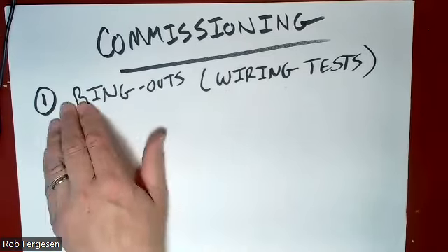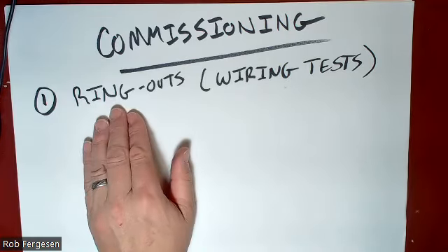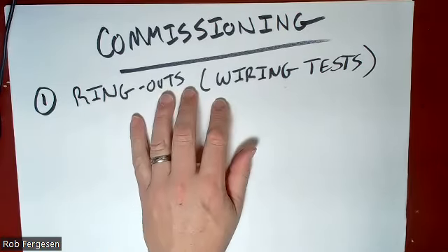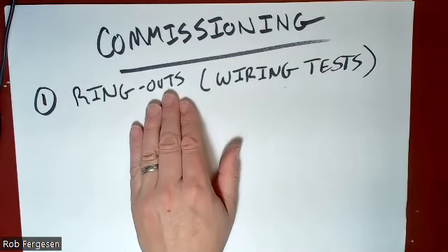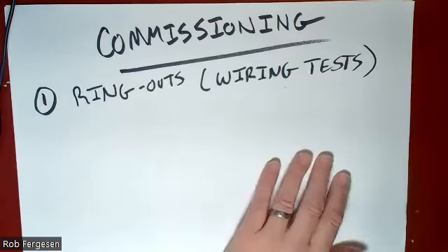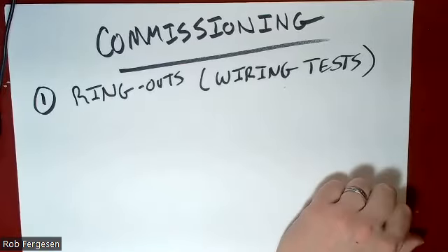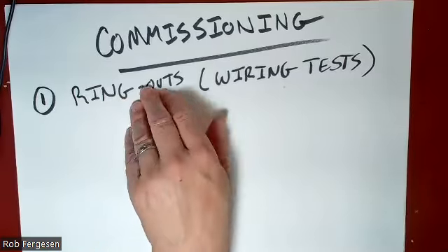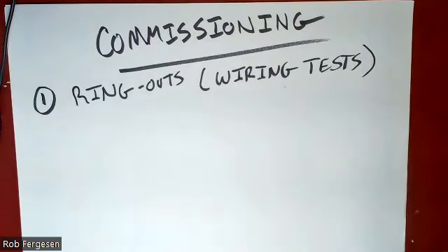However, the ring out thing is becoming less and less of an issue in our world of commissioning because of the greater number of Wi-Fi or Ethernet integrated sensors and different instruments and different kinds of controllers. We have a whole lot of equipment now that'll just hang off the Ethernet somewhere or be wireless. So the old days of spending days doing ring outs and wiring tests is starting to fade into the past.